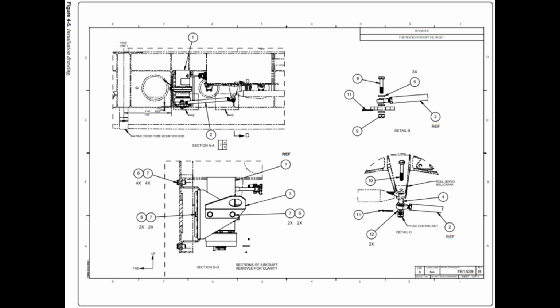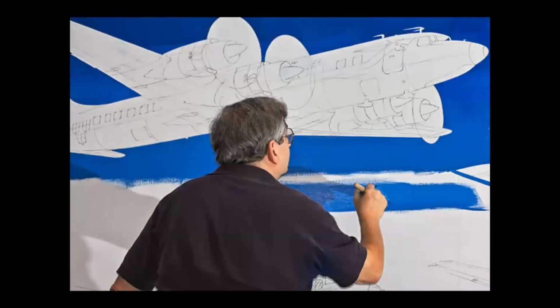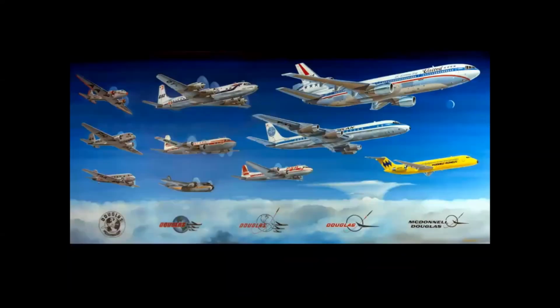Other numbering systems provide a separate box preceding the drawing number for the drawing size identifier. In another modification of this system, the part number of the depicted assembly is assigned as the drawing number. Drawing standards. Drawing standards cover such items as paper sizes, notes, numbering systems, geometric dimensions and tolerances, abbreviations, welding symbols, roughness symbols, and electrical symbols.